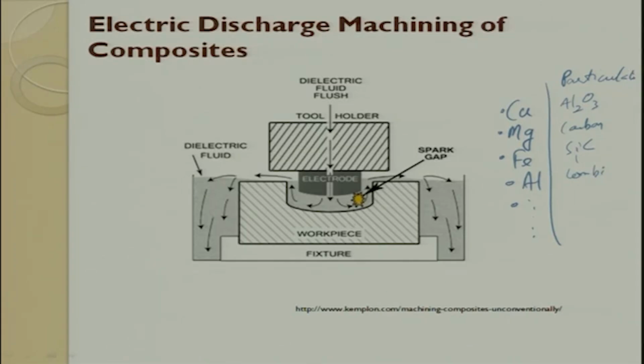Here, since there is a lot of heat between the electrode and the workpiece, there is a spark going to happen. So, there is a temperature phenomenon. Heat is applied and then there is a subtraction process which happens here. It is pretty interesting because in metal matrix composite you will have reinforcing agents also there. If the matrix melts, these are the particulates. So, if the matrix melts off, then the particulates also drop. Depending upon the volume fraction, you choose a proper process parameter and then you try to do it.